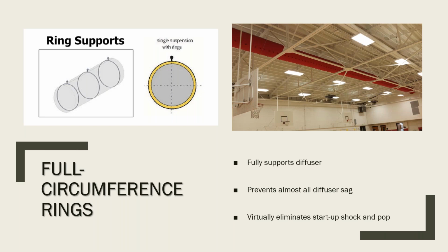So in this picture you would see this is actually ring supports, the air is off, and it looks like the air is on. That's actually what you want the fabric duct to look like at all times. So we manufacturers do strongly support using internal ring supports.